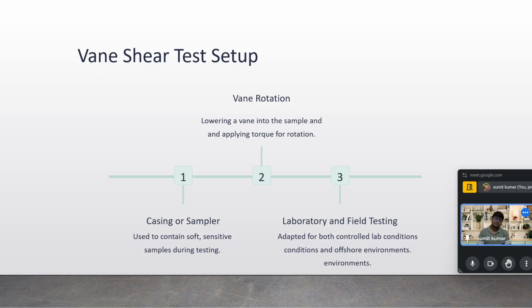Second, the vane rotation is applied. First, the casing or sampler is inserted in the soil. After that, rotation is applied, lowering the vane into the sample and applying the torque for rotation.